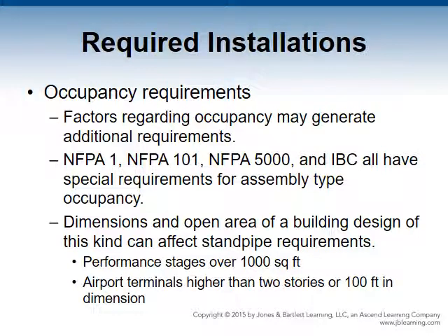Occupancy requirements. Factors regarding occupancy, such as occupancy load or lack of other fire protection features, may generate additional requirements. Assembly occupancies often generate additional requirements, as listed in NFPA 1, 101, and 5000 in the IBC. All have additional requirements for this type.